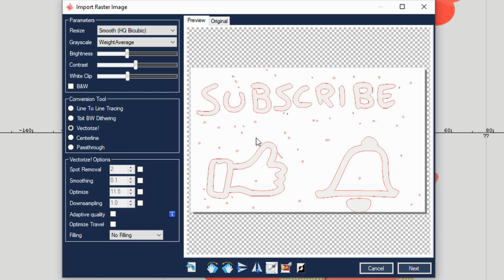The first thing is, you can see here we have these dots, and we don't really want that in our engraving. So we can remove the spots. So click on spot removal and crank up this number. As you can see, as I go up with the number, more and more spots are disappearing because this is matching the size. Okay, so once you're happy with that, you can stop.